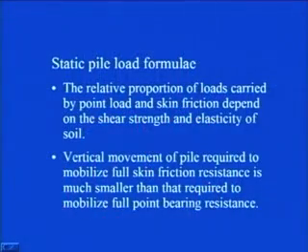And then the vertical movement of pile required to mobilize full skin friction resistance is much smaller than that required to mobilize full point bearing resistance. This is a very important aspect, which is that the vertical movement of pile required to mobilize full friction resistance is much smaller than that required to mobilize full point bearing resistance.